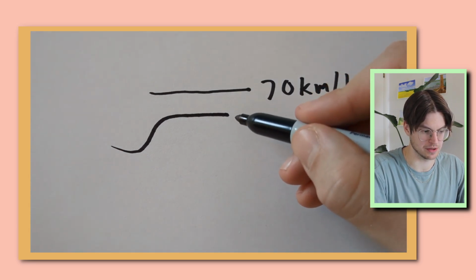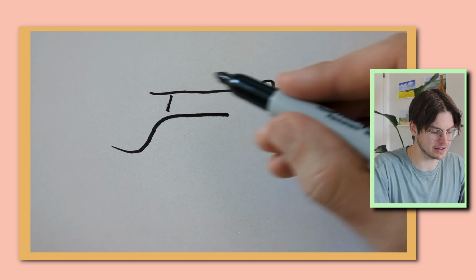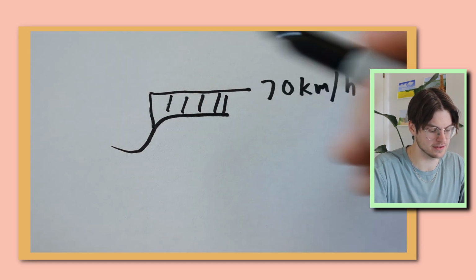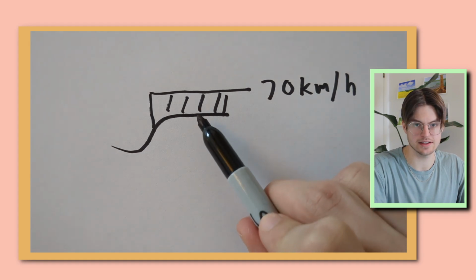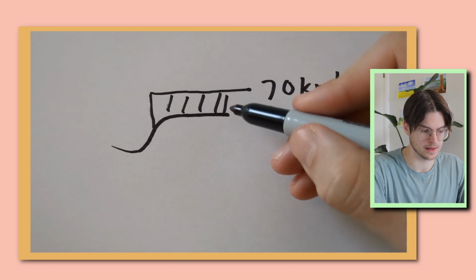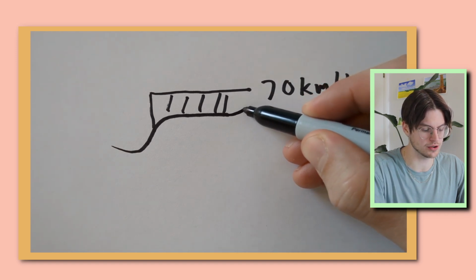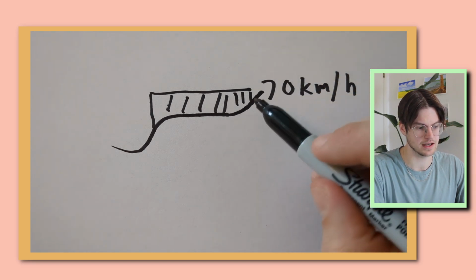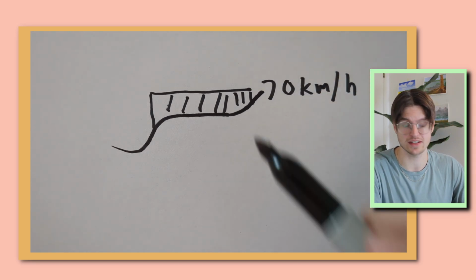And we're stuck here with the P. But the I regulator, it integrates this error, the area here, right? So as soon as this area is not 0, it will grow. So it will push up till it reaches 70, and the area stops growing, that's the only time it gives up.